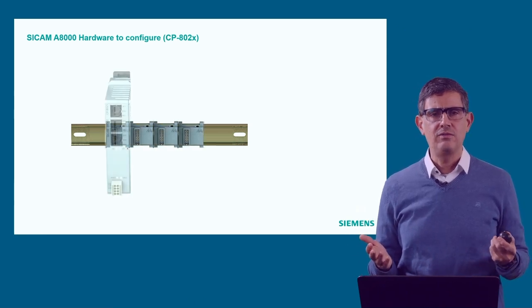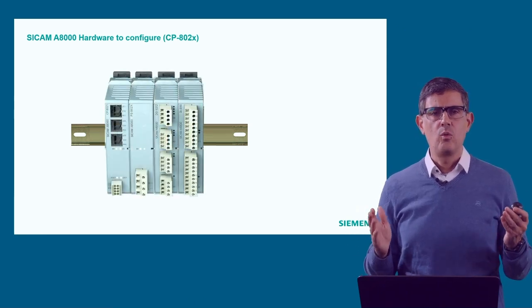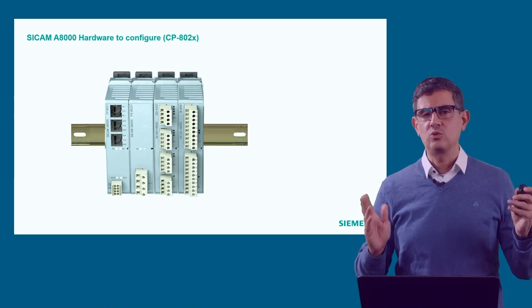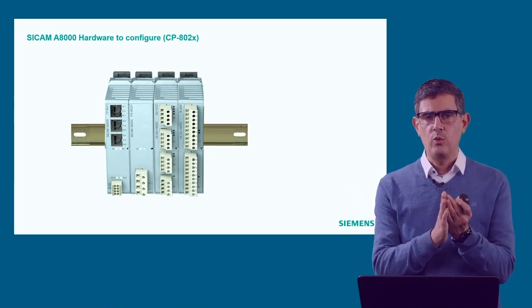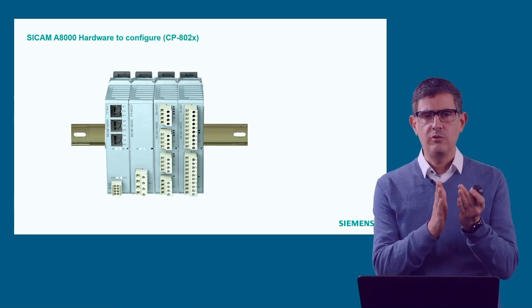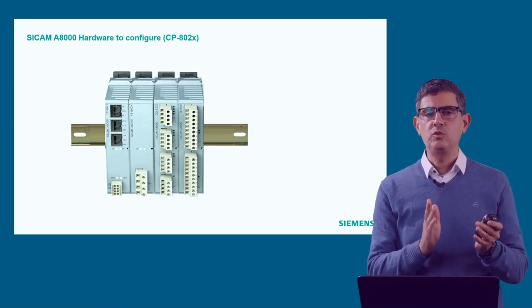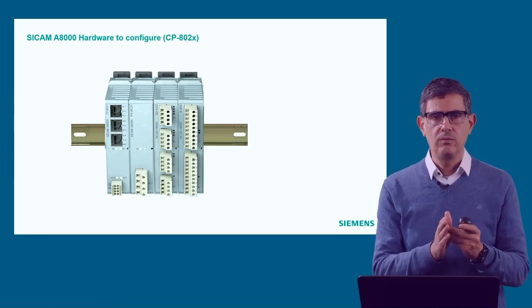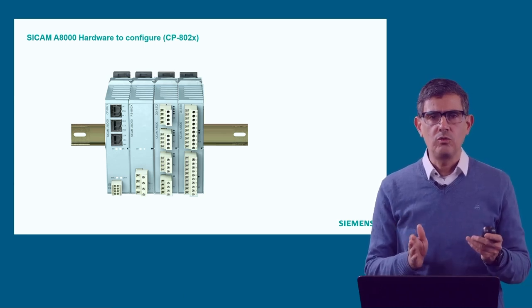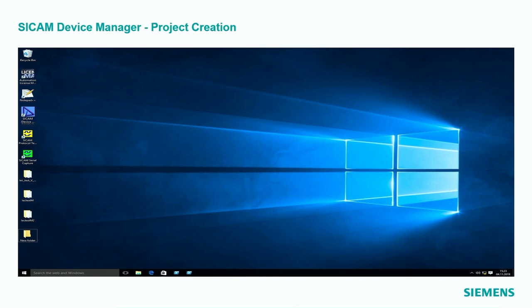We will have one CP8021 or 22 connected directly with the power supply, and from there we will have one module for the binary outputs, DO8212, one module for the binary inputs.